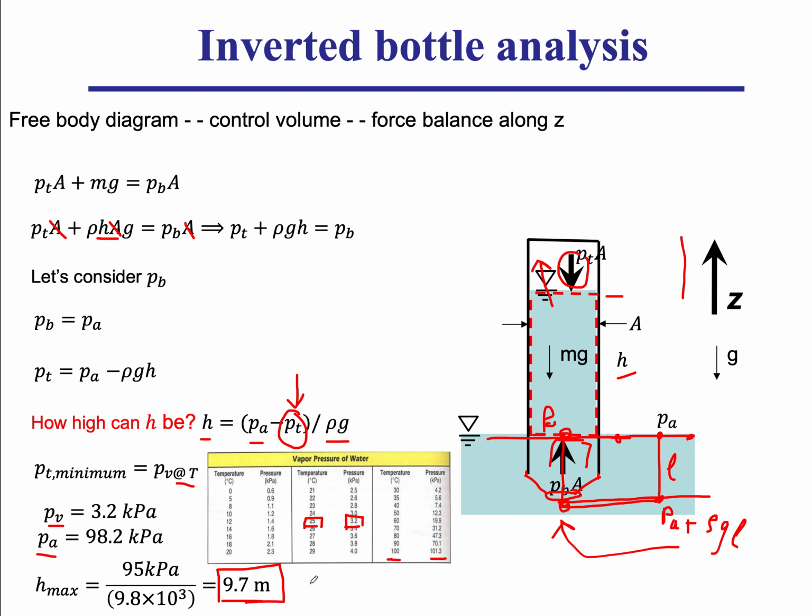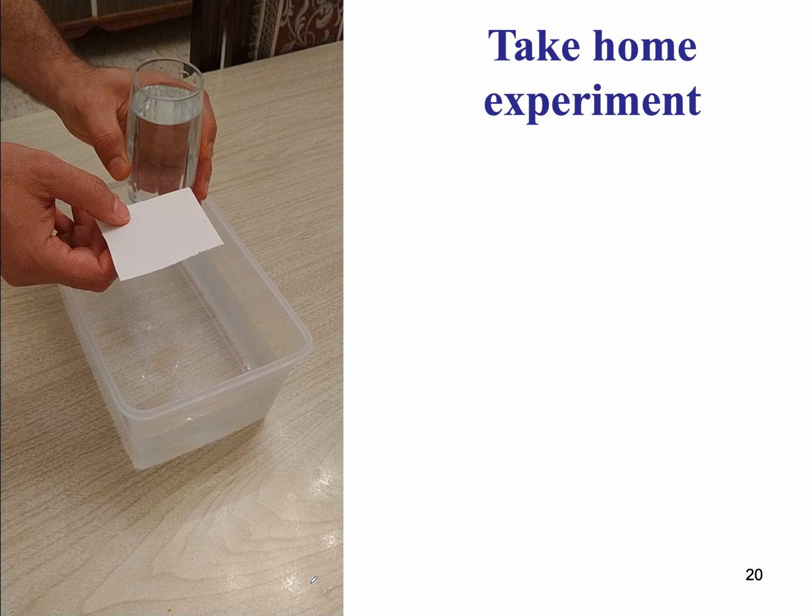We don't call it boiling, we call it cavitating, because we're not adding heat, we're just changing the pressure to induce a change in state in the water, a thermodynamic state. Okay, so the atmospheric pressure is actually an important quantity that now seems to be affecting our industrial processes, and we would like to look at it some more.